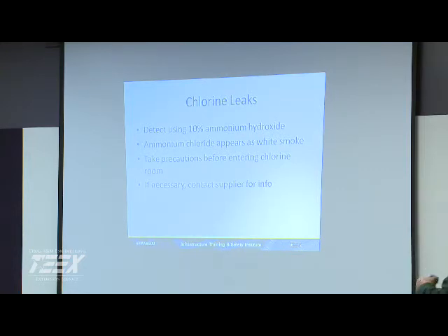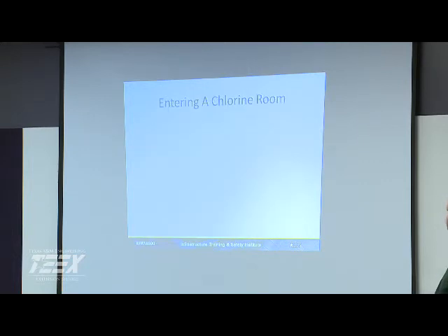The Chlorine Institute is a real good source if you have questions on chlorine leaks. If you do have a leak and you don't know how to deal with it, you can always contact your supplier. Talk about entering a chlorine room. Training is important. You need to have either supply air or SCBAs. You gotta have somebody there to help rescue you in case you get in trouble. You gotta have the right repair equipment.